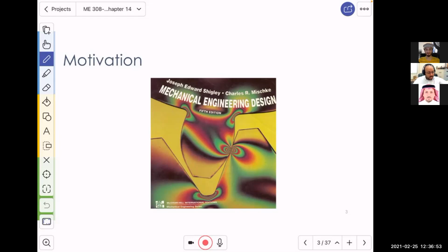So it filters out all other light spectrums, you know, the red, the green, the yellow, and lets monochromatic light pass through the polycarbonate. The result that you are going to see out of that is this. What are these? These nice round butterfly-looking colors. These are called the fringes, and they are directly related to the state of stress of the material.